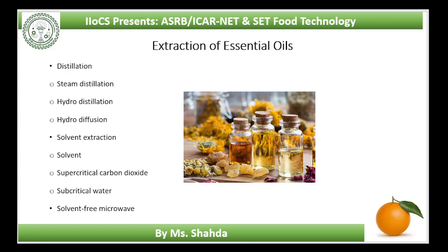A new process design and operation for steam distillation of essential oils, to increase oil yield and reduce the loss of polar compounds in wastewater, was developed by Masango. The system consists of a packed bed of the plant materials which sits above the steam source. Only steam passes through it, and the boiling water is not mixed with the plant material.